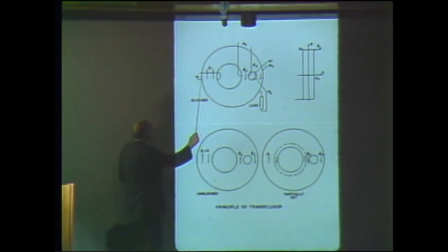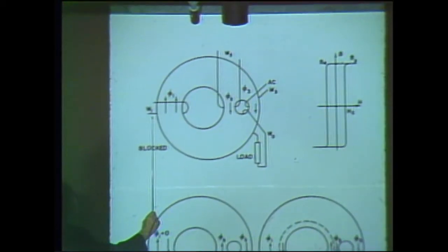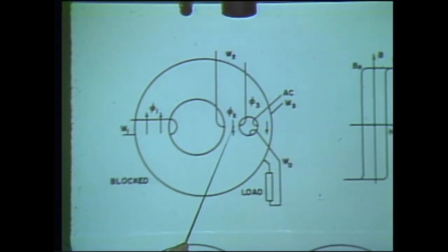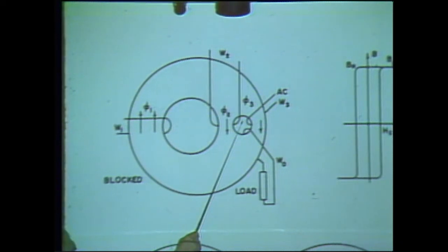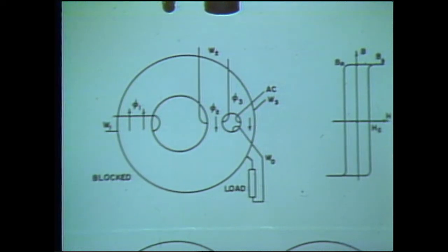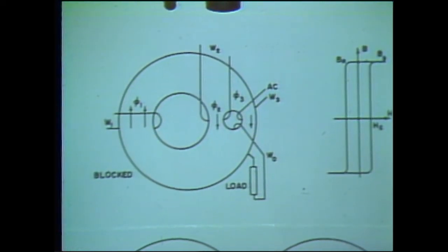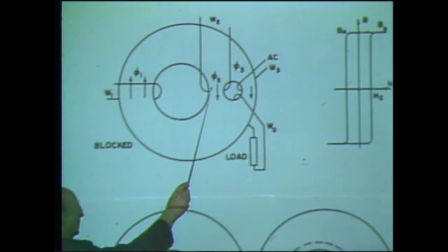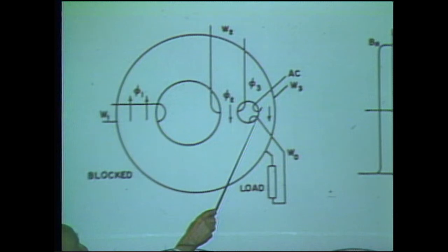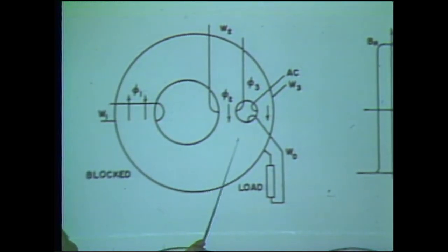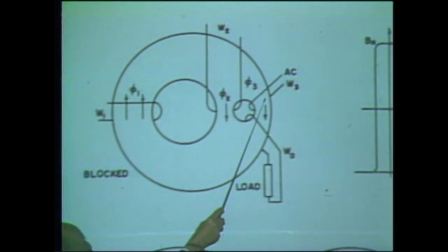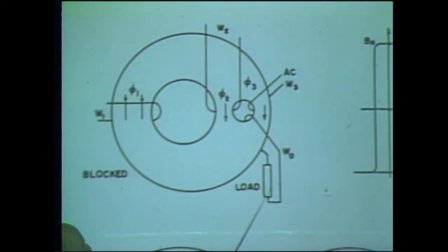The idea here is that if you put a very heavy current in this winding, magnetize the whole business this way, then if you put a smaller current through this hole, which tries to change the magnetization around the small hole, it won't succeed, because either you are trying to push the flux clockwise, and you can't increase it because it's already saturated, or counterclockwise, you can't succeed either because it's saturated here. So therefore, you put an AC here and there's no voltage on the output.